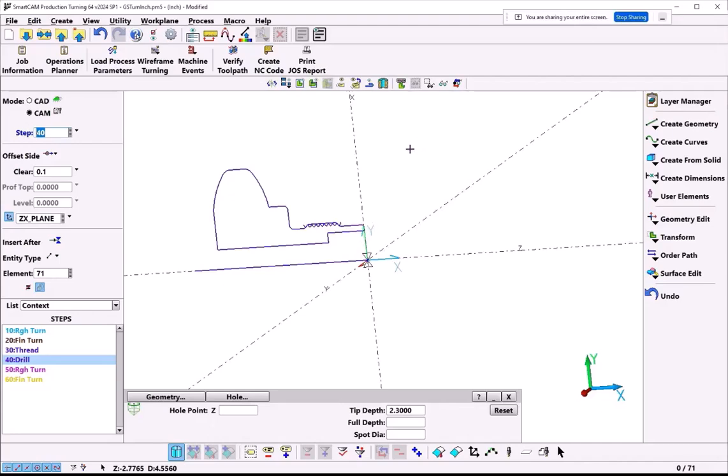What I'm worried about is if it had to go in all the way to here, it would wrap it from there down through the part, crash through the part. But I think we'll be okay because the tool's up here and it's going to start cutting the mouth, so it'll wrap it down to here, still out in front of the part, and then it'll start roughing. But we're cutting pixels, so if we cross through our part, we'll be able to see it without damaging the machine or a tool.